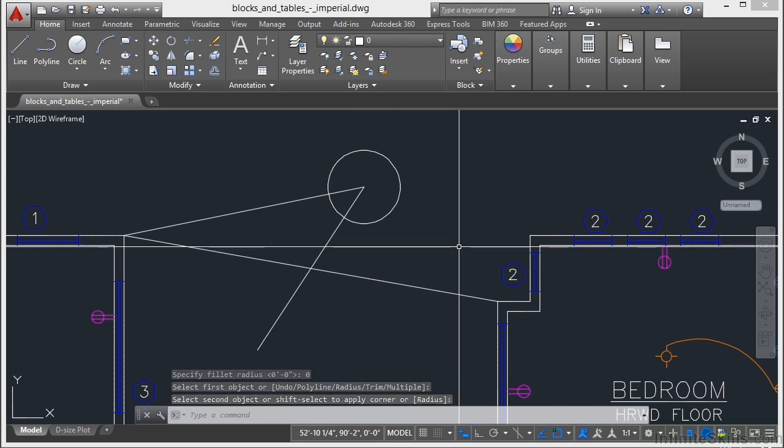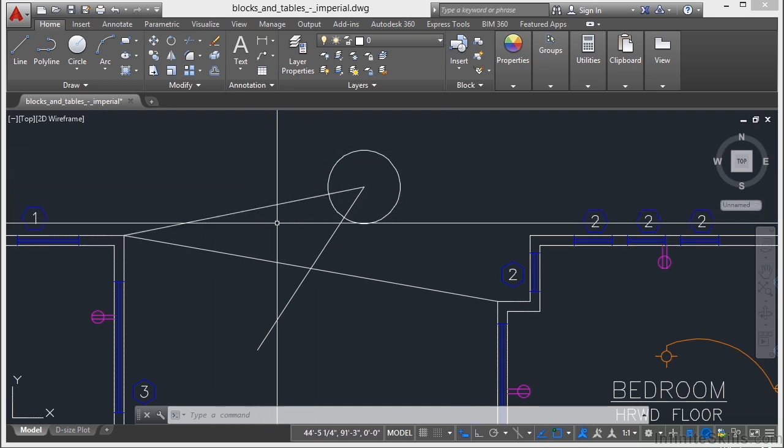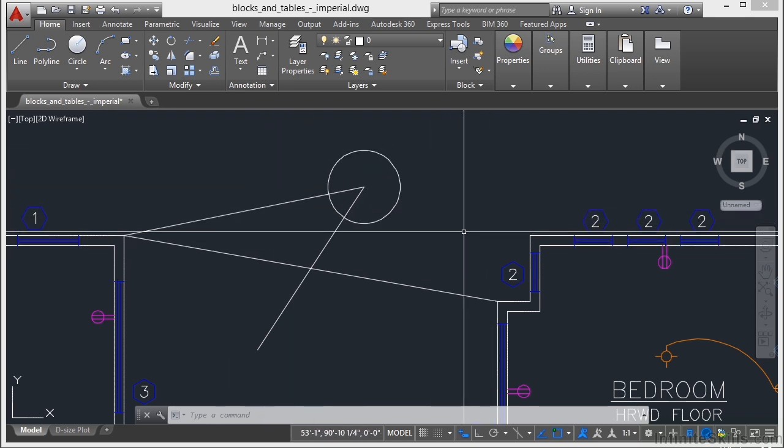So that's a really cool tool to use with your Object Snap tracking because it allows you to place objects where there are no objects, and it eliminates the need for construction lines, extension lines, trimming lines, filleting like this. To go back to that line, I would have to trim these again, and there's a lot more work available to you. Now, by doing it this way with that Object Snap tracking, you eliminate work, you get done more quickly, and that's the point to CAD.